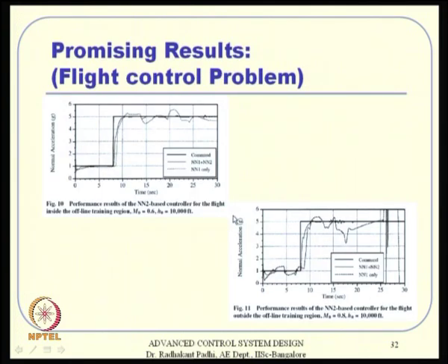Now, as a representative result, you see that without adaptive control, this is not behaving very well. So, this is a commanded signal sort of thing, but with adaptive control, okay, this NN1 plus NN2 neural network 2, that is the adaptive control part of it, this is very close to the commanded value. You do not see any deviation at all. The moment this plant is something different and all that, it tries to adapt very quickly rather. Okay. And the same thing happens also here. You see the error between this solid line and this particular thing is so small, whereas if you do not have the adaptive control, this is going very far off actually. Okay. And several results are there in a number of papers that I told you about before actually.